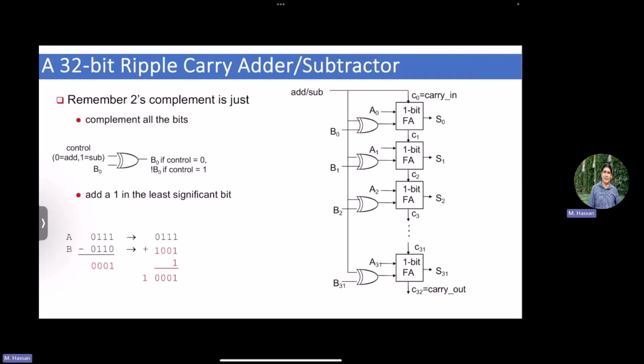What you do is you add a bit that's called the overflow bit, right? The overflow bit is simply detecting whether your result exceeds the maximum width of the machine or not. How to determine this? Simply look at the last bit. If you have a carry out of the 32nd bit, that means this carry would go to the 33rd. That means you have an overflow, right? So the simple circuitry for the overflow is to take the carry from the most significant bit of the addition, right? If I have an overflow, what do I do?